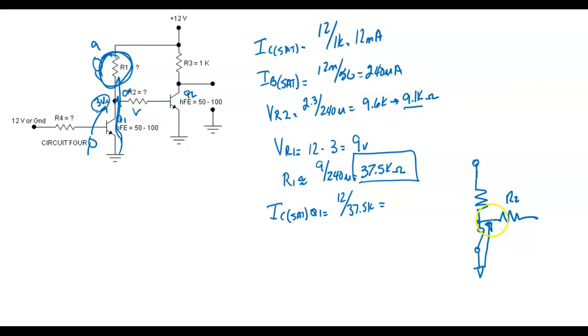So that means we have approximately 0 volts right there. Right? You understand? To get this circuit right here to work, we've got to have at least what right there? We've got to have at least 7/10, actually more, because 7/10 of a volt would try to conduct, but then this guy here would drop it below 7/10 of a volt, so we'd still be cut off.